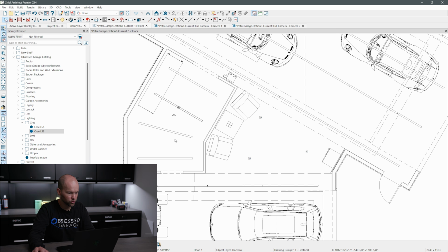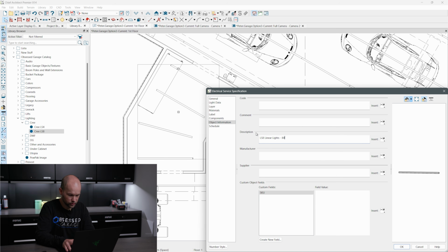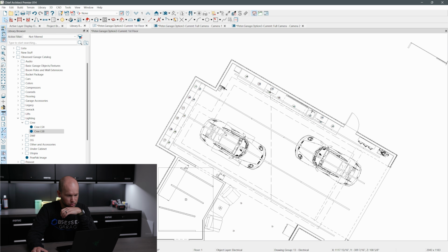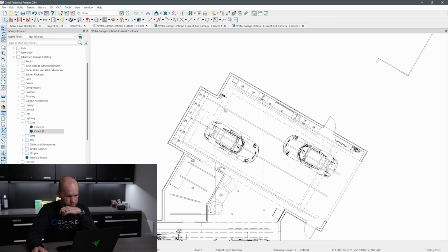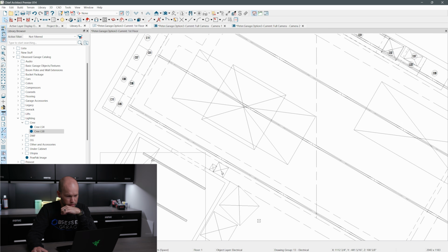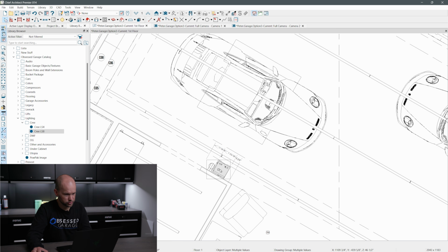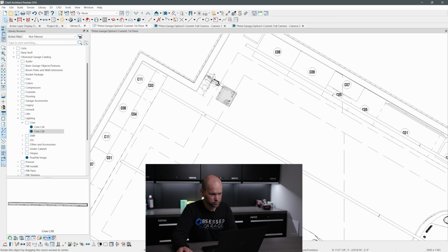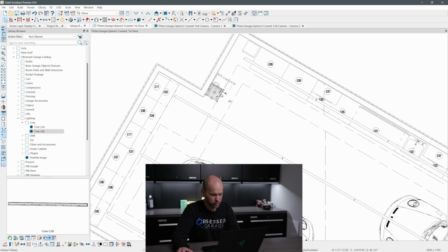And then we'll do a couple this way. Because it's so concentrated now, we'll probably do lower lumen output fixtures. This is going to be the 8,000 lumen variant. One thing that still needs to be modified is our lift control placement. Maybe over here makes more sense rather than on this corner. Yeah, let's go ahead and do that. This is part of our last step here of tidying things up, making sure that everything looks right, and other little details like this are good to have correct.